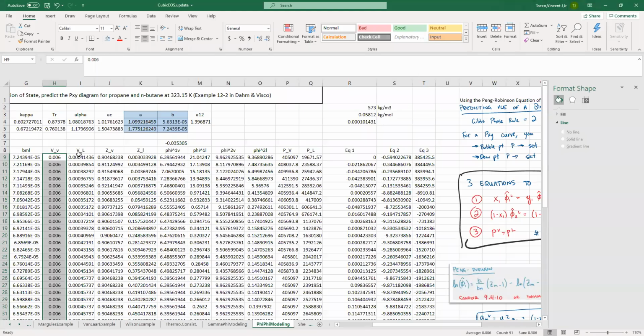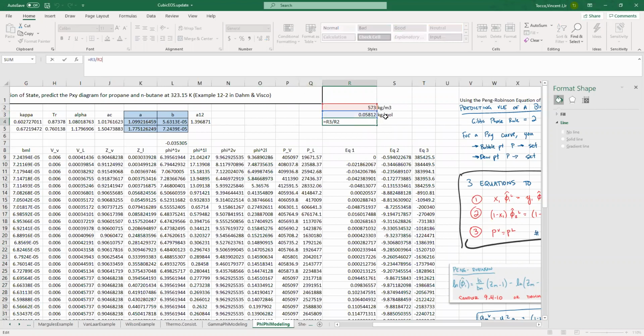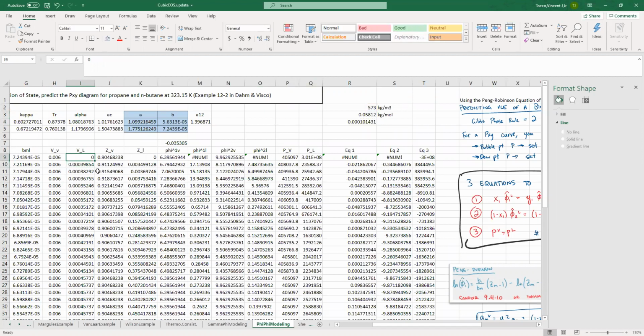All right, I wanted the molar volume of the liquid for pentane. So what I did is I looked up the density and the molecular weight, converted them to the proper units, and the molar volume should be the molecular weight divided by the density. So let's plug this in and see if it'll give us a little more accurate initial guess: 0.000101.